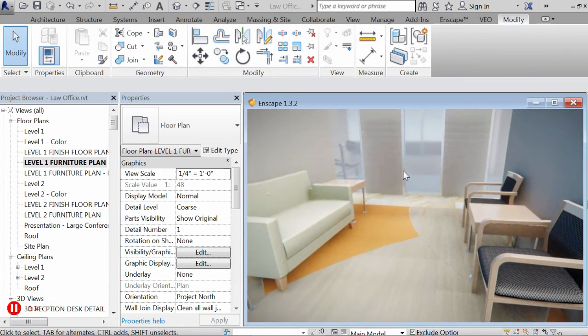And it seems like you get a lot more control from it. I've had issues where the filled region can blow up if you start editing the floor sketch, whereas this is just going to stay put. You obviously have to fix it, but it's not going to automatically delete itself or something.